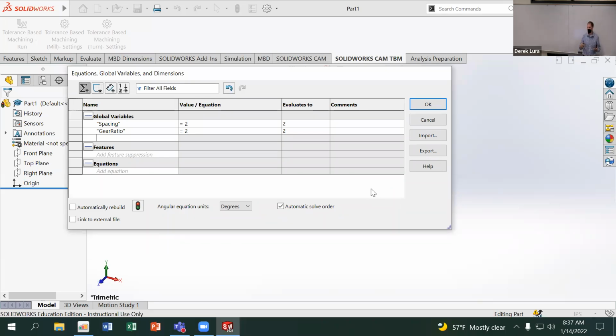You need to have about 12 teeth to get an efficient profile. So a lot of times that ends up being a limiting factor. Once you start getting to 100-to-1 or something like that, you either need multiple gears or you need to move to something like a worm gear or a different type of gear set, right? So the gear ratio here should be some reasonable number, right? Not huge, not tiny. Closer to 1 being typically more efficient.